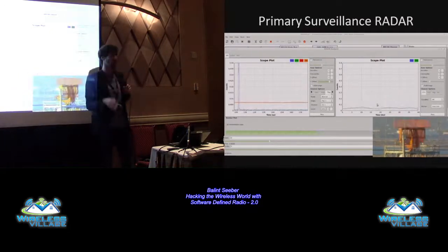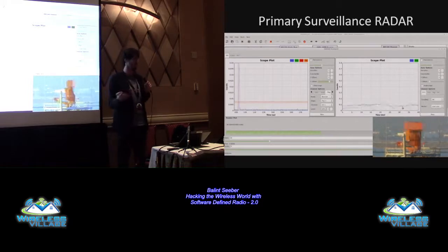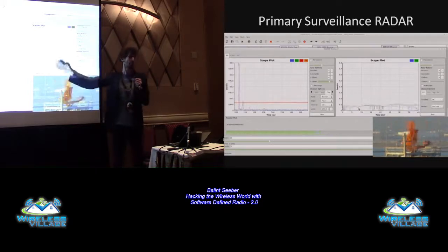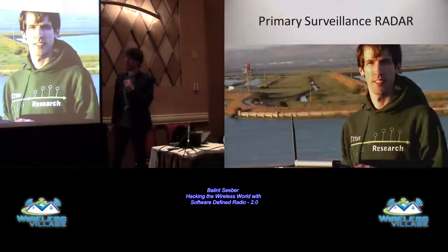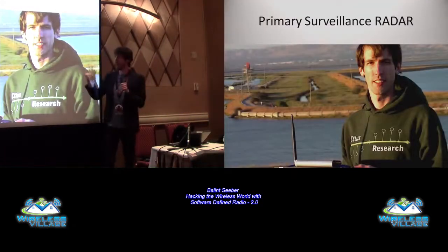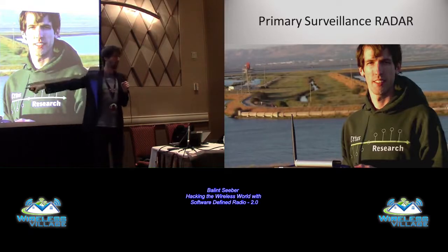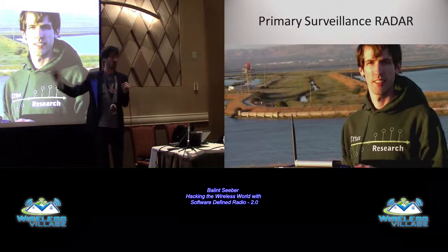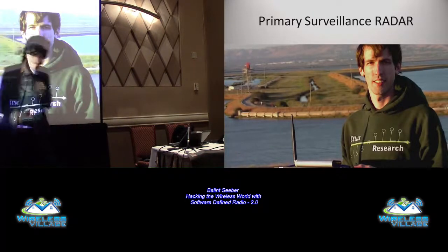Just if you can see there's some other stuff that happens. And I thought, well, hang on a minute. Could that be radar returns? They're probably going to be close in from ground clutter and buildings and so on. But there's clearly stuff coming back. And I thought, well, maybe you can plot that. Now, just remember, for this entire bit, all I'm using is this little radio and that omnidirectional whip antenna. I'm not using a directional antenna with lots of gain like that. That's the next step of the project.